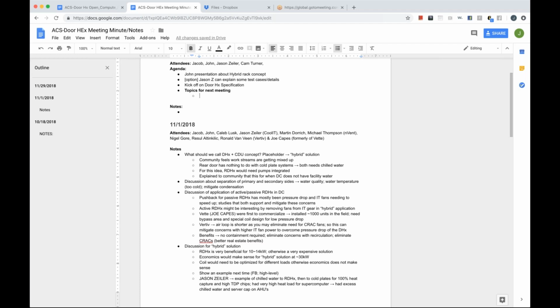No, the cold plate group is definitely not using facility water on the server side of the CDU. There is the assumption that the CDU will be served by facility water, but the water in the rack will definitely be a closed loop. And the cold plate team, at least at the present time, is stopping at the server. So what's inside the server, or inside the box, can be proprietary, but what we're looking at is consistent connections and pressure and temperatures and those sorts of things.